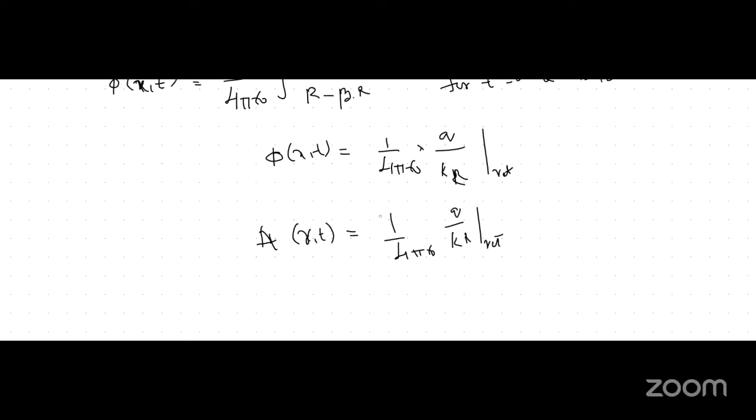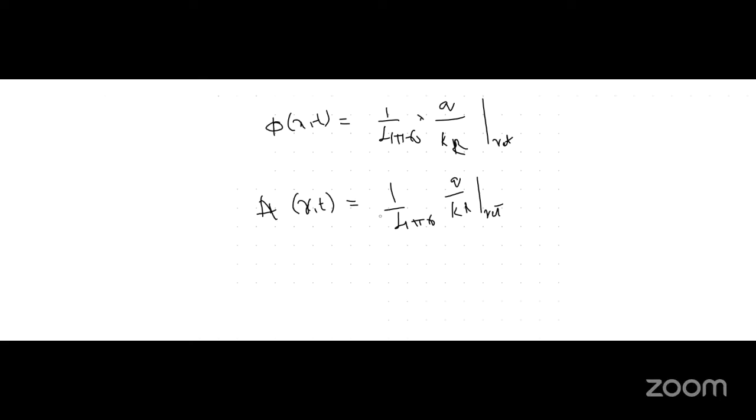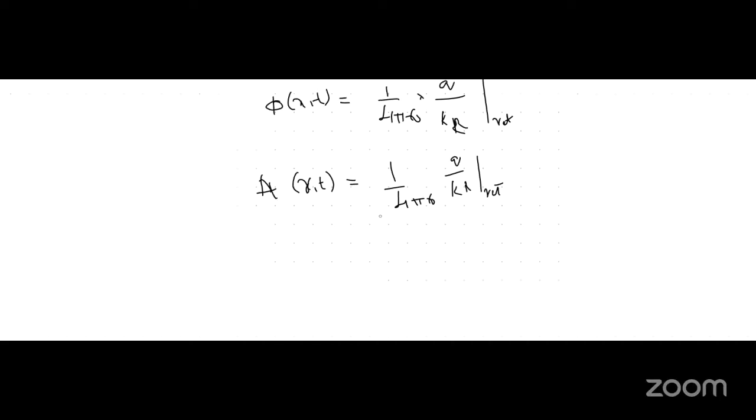Next, we will see another topic, which is the center-fed antenna. In this center-fed linear antenna, we consider two thin wires of length d by 2 each, oriented along the z-axis, with a small gap at the midpoint. So we draw that one.